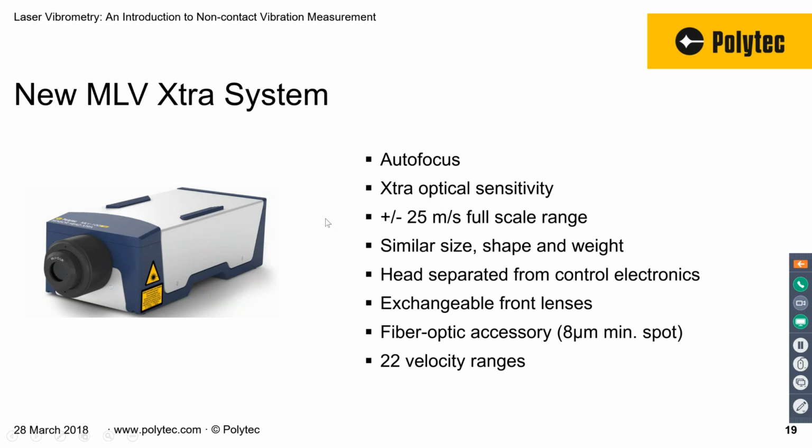So we can get a higher power laser impinging on a surface, which means that even for very poorly reflecting or very distant surfaces, we get sufficient return signal to make a very high resolution signal-to-noise measurement of the vibration. So it's particularly applicable for extreme applications where you get very poor reflectivity from the surface.